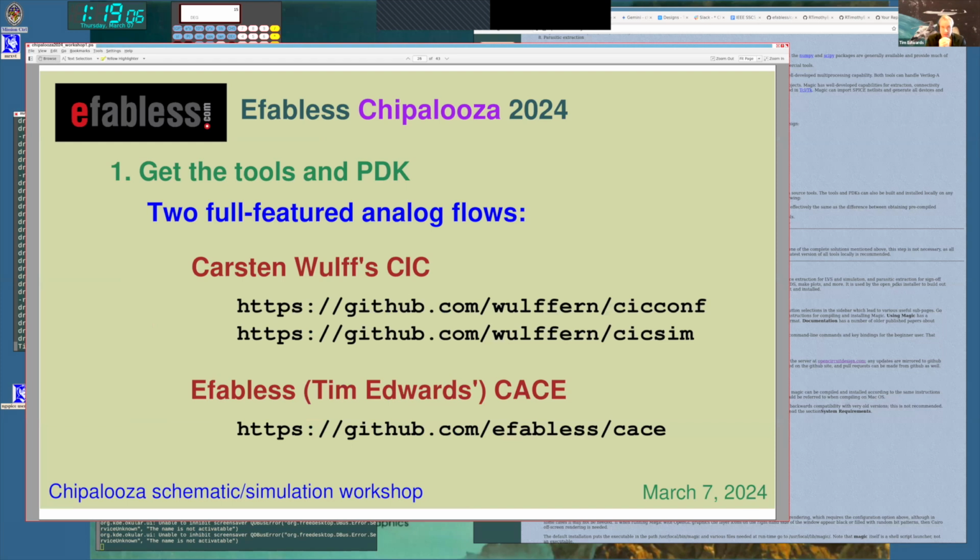So now this thing about the automatic datasheet generation. I know of 2 systems right now. One of them is one that I developed myself called Case. It was developed about 5 years ago or so on the eFabless platform. The reason it's not very popular is because it was restricted to the platform, because I was using it with the XFAB fabrication process, and some of that was semi-proprietary PDK information. So all of it was pretty much restricted to the platform.